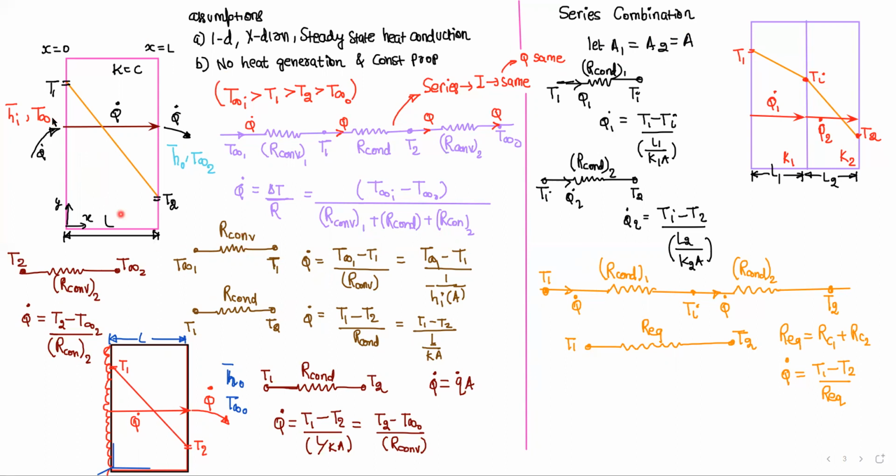So in this case we have the heat transfer by convection on both sides of the wall. There are some cases in which one side is having heat generation, then conduction and convection. For example, this is some heating element that is generating heat, so the temperature is T1, and at the other end temperature is T2, and as T2 is greater than the surrounding temperature, heat will be transferred from the right wall of the slab to the surrounding.